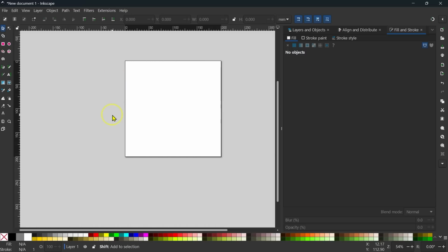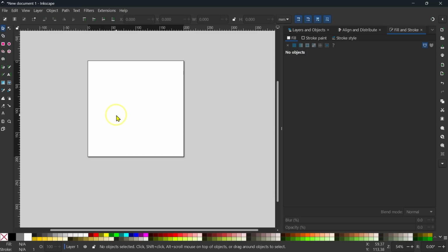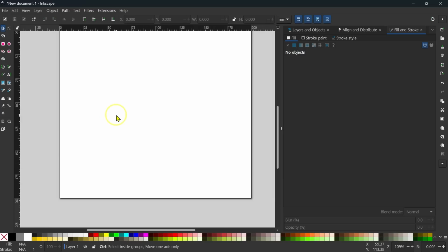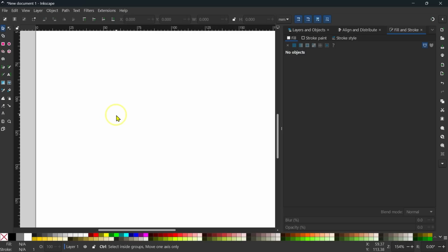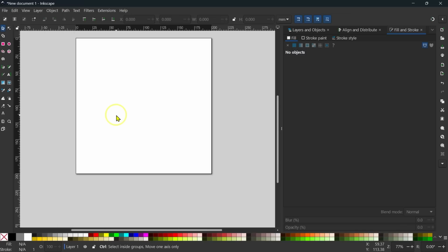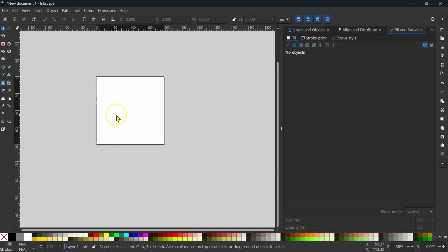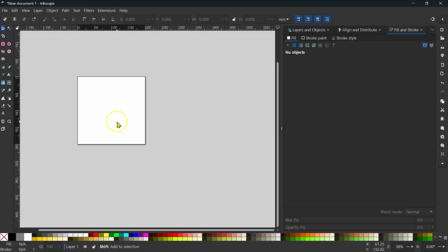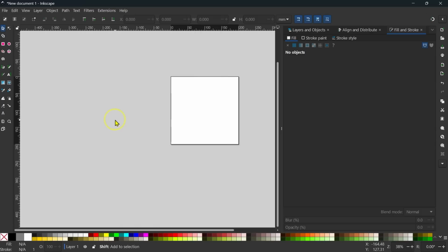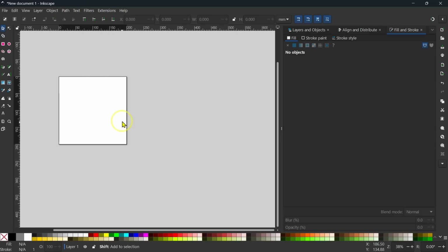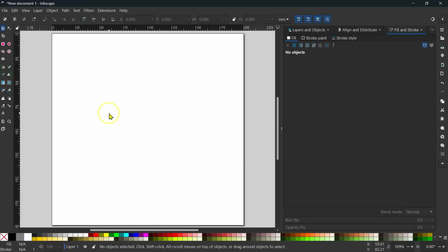You can practice them. Let me show you one more time. Control, front mouse: if you scroll to the front, it will zoom in. If you scroll back, it will zoom out. Alt key, nothing. Shift key, it will pan left and right. If you scroll front, it will go right. If you scroll back, it will go left. And zoom, as I said, the shortcut was 5. If I press 5, it will zoom the page again.